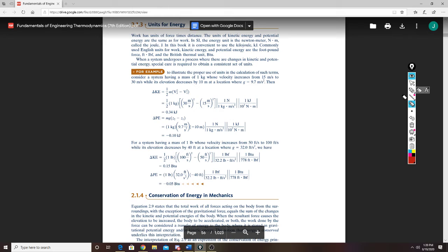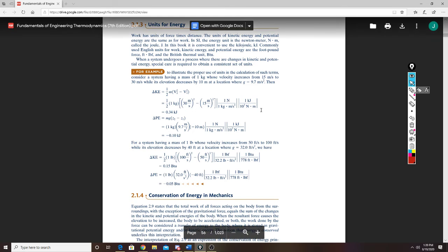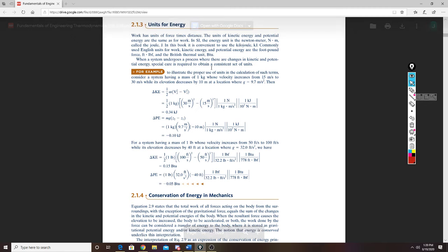And this is just a conversion to show you how much energy there is. So right here, as you can see, if you drop this, it had 10 meters high, right? So they had it 10 meters high, a mass of 1 kilogram. You got 10 kilojoules as an energy off of it. So as you can see, the values of the energy are fairly low, unless your mass is really high and your differences in height are really high. So that's why they're often neglected. I mean, 10 meters up is a decent fall.